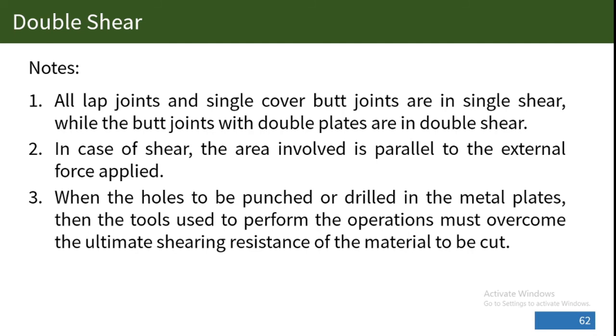So these are the areas parallel to where you apply the force. Right? So that is the area of interest when we are punching a hole in a metal plate or body. And also, when doing so, it must overcome the ultimate shearing resistance of the material. Okay.